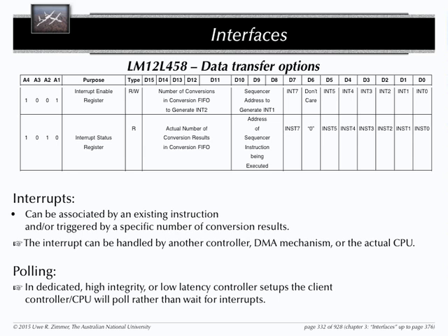Polling is not a slow operation, but it's a very CPU-intensive operation. Polling means that you're not going through the whole cycle of triggering an interrupt, getting a context switch, saving all the registers, blah, blah. Polling means that you're staring at a single memory cell. Is this conversion done? With the full speed of your CPU, the moment this thing is done, you will get it with the next CPU cycle. Now, you cannot get any more responsive than that. This is more responsive than going through an interrupt. Counterintuitively to what most people think, this is faster than going through an interrupt.